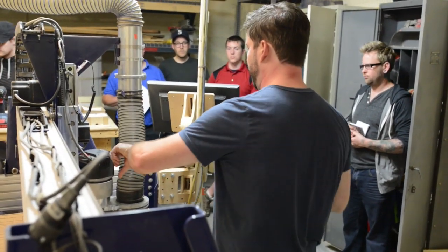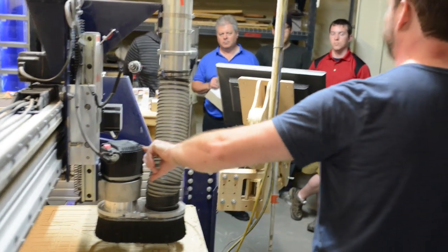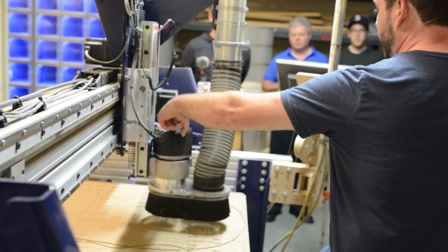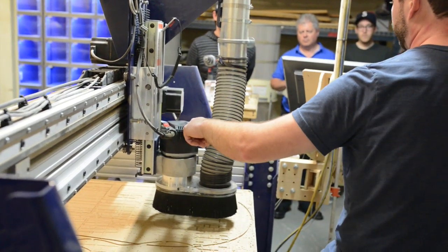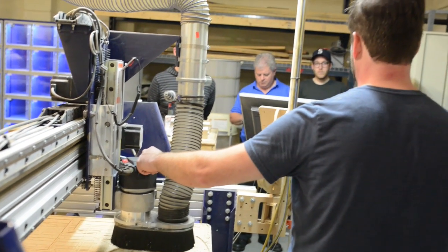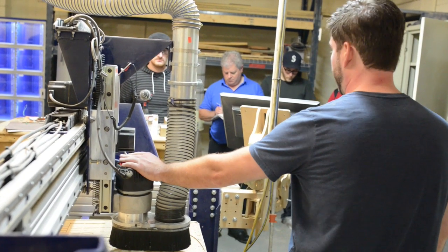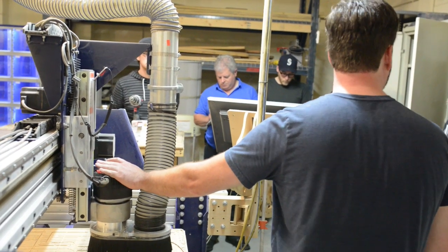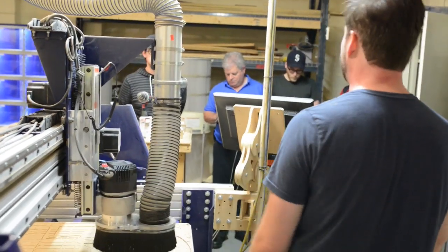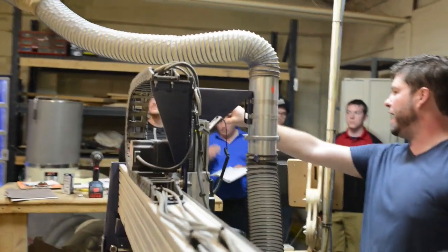And remember I talked about the spindle speeds? This is how you change the different spindle speeds. So all the way from 10,000 RPMs up to 21,000 RPMs. For wood, you would never ever go above 13,000 RPMs. So that's the bottom two slowest speeds. Anywhere around there, I'm almost always at 13,000 RPMs, so you'll be fine anywhere around there. And this is the dust collector. We'll be turning that on later.